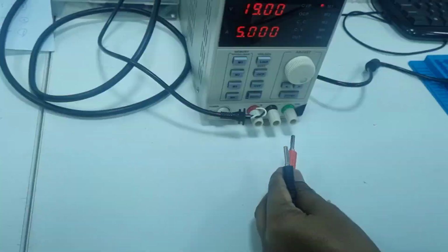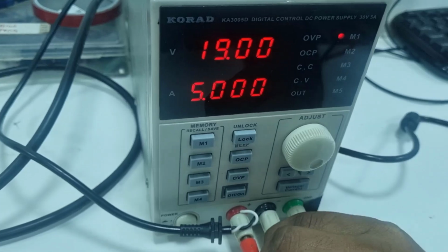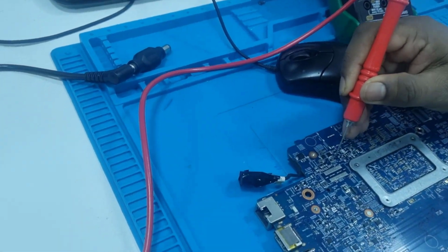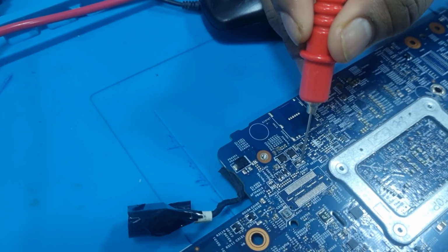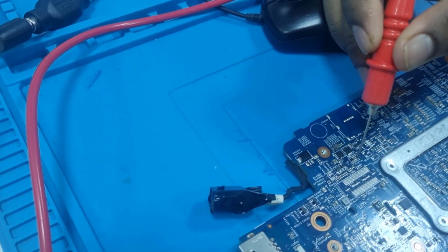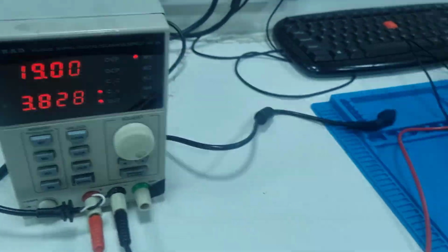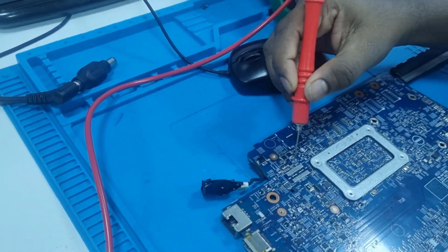And these probes we are going to put on the DC power supply, positive and negative, with one probe to the ground, and that positive probe we are going to connect on the current sensing resistor, okay. As soon as I put this probe to the current sensing resistor, the current shoots to 5 ampere, and with the other hand I have to check which component is getting hot.